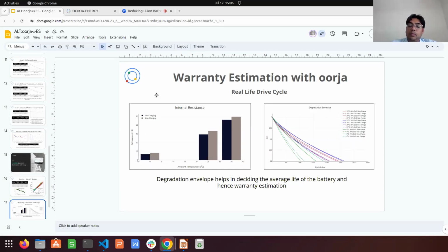And what happens is that with the hybrid models, we can make use of this RPT test data and train the models. Eventually, if you are doing the subsequent cycling on the new cells, we can choose not to have the RPT cycles present in the testing. Based on the trained models, you can replace the RPTs completely and predict your state of health based on the trained model itself.